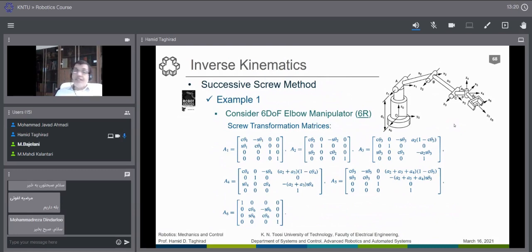Of course, it is easy because all the parameters are rotational, all the joints are revolute, and we have a 6R manipulator. It is not the most general 6R manipulator, since we have 2 intersecting axes at the wrist, but it is quite an extensive problem.